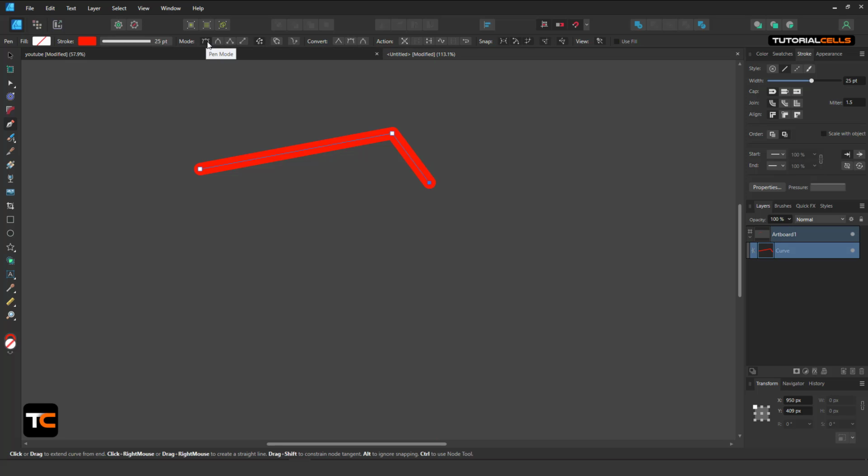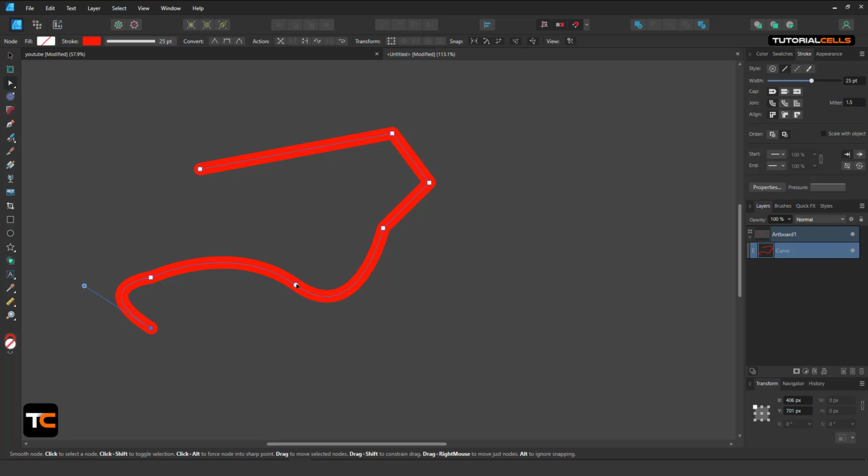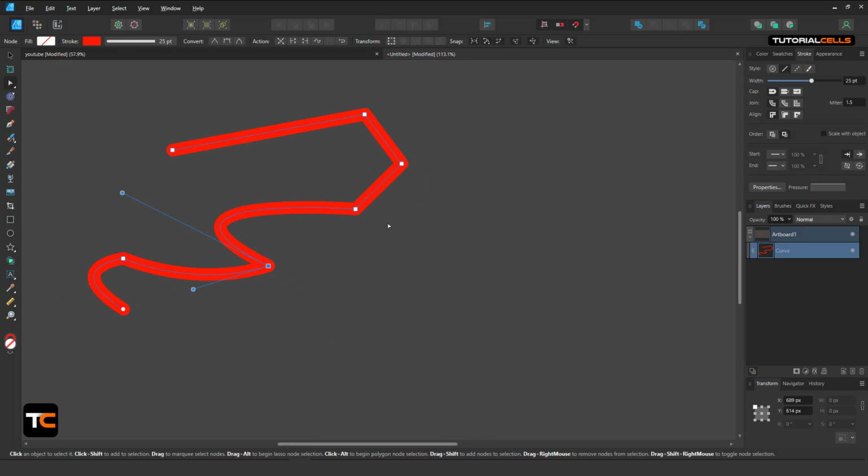In this mode, we have two modes: polygon mode combined with tangent mode. When you just simply click, it creates a polygon. When you click and drag, as you can see, we drag out tangent handles. And then the second click will create another tangent for you. Then click and drag. And after that, you can come back and modify this tangent. With this tangent, you can hold Alt and break the tangent. Holding Alt to break the tangents. Nice. This is the tangent mode of the pen. It's very simple.